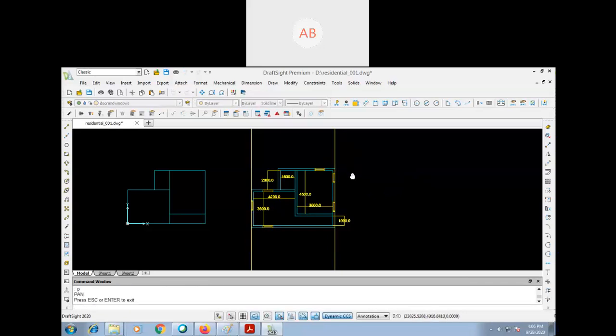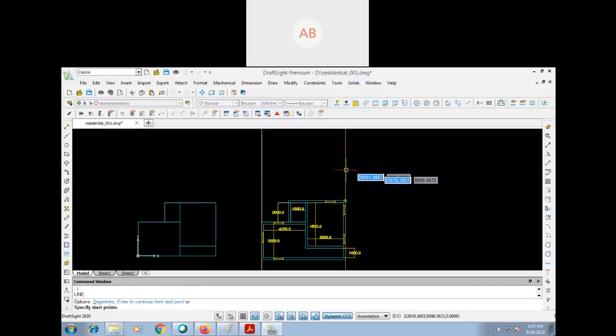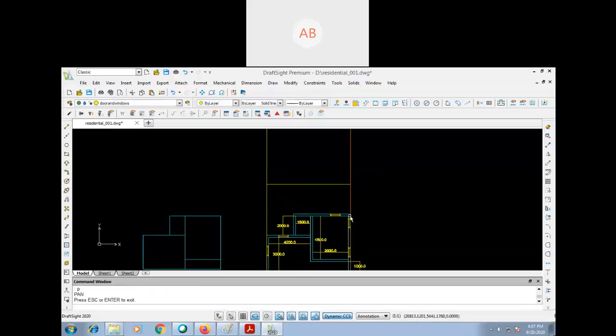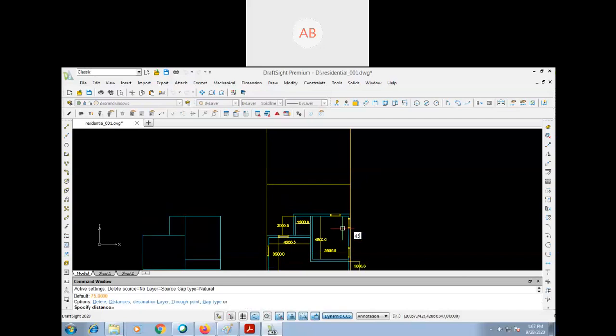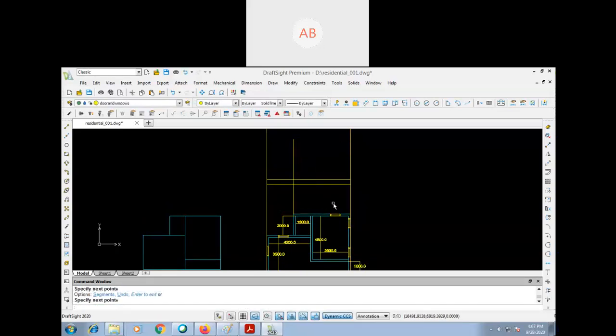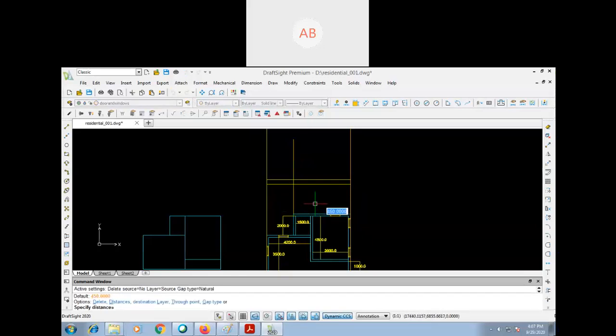This one. So this will be my wall to wall outside if you're going to draw the elevation, right? Then you have a plinth height of 450. You can offset that line to 450, this one, and then just follow the projection of these lines. Okay, then what is the height from the first floor up to the ceiling? This is 3,000. So 3,000. Okay, so you just trim this part.